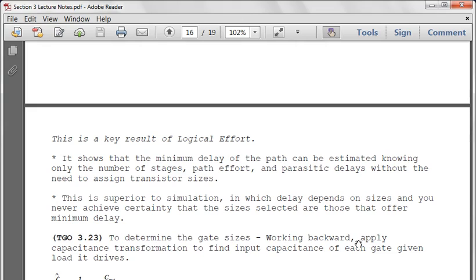You have to worry about the logical effort of the full path. You have to store everything in registers. You can have a minimum and maximum, so you have your minimum value stored in your registers, you have a comparator, you have maximum registers, you have your Fahrenheit to Celsius converter, and you have your control signals controlling the whole data path. So you have to worry about all of these when designing your circuit.